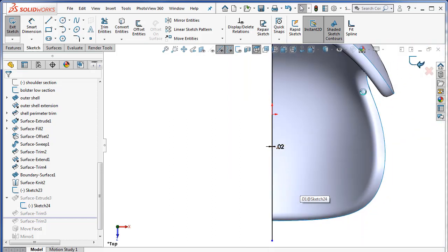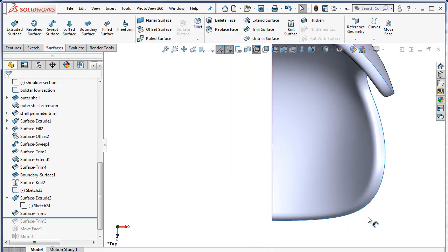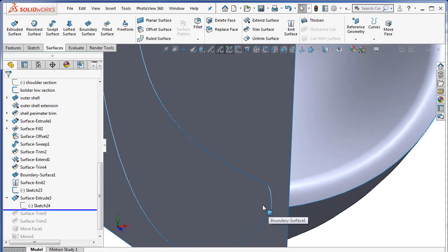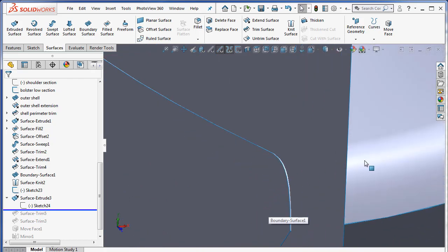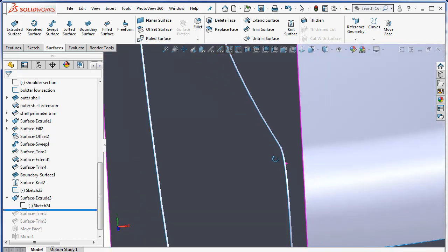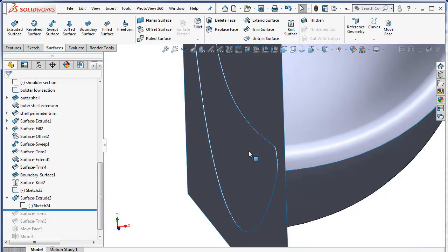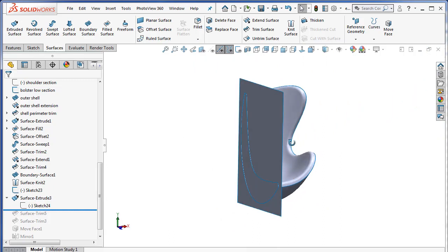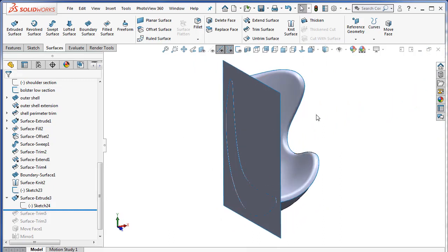So getting out of the sketch, and rolling back, I want to just show you what this looks like before trimming. And we can see that the seat surfaces are just barely passing through my extruded surface. When you're doing a mutual trim, this is usually the desired situation, that you don't want surfaces just to stop on other surfaces.